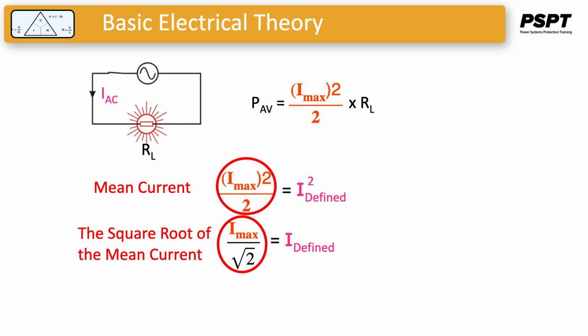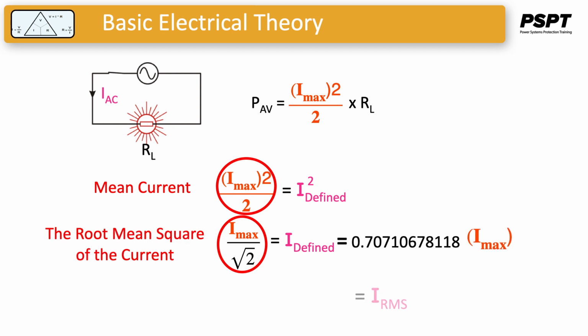This is another more useful way to describe AC quantities, voltage and current, and of course it can be converted directly to amplitude, peak, peak to peak, or average just by multiplying by a scaling factor. However, we use RMS values for current and voltage. We can directly calculate the average power from these root mean square quantities.